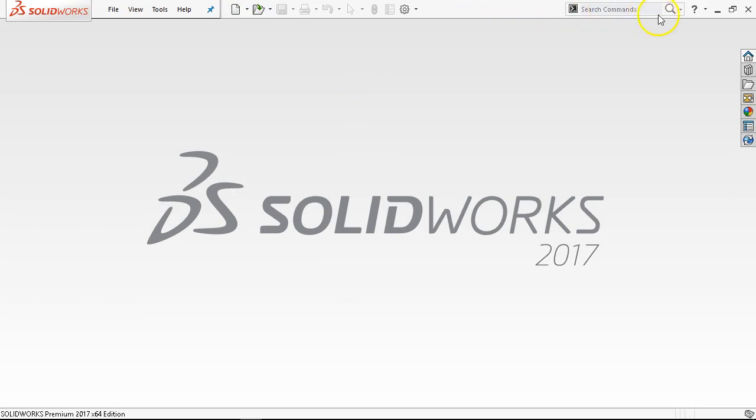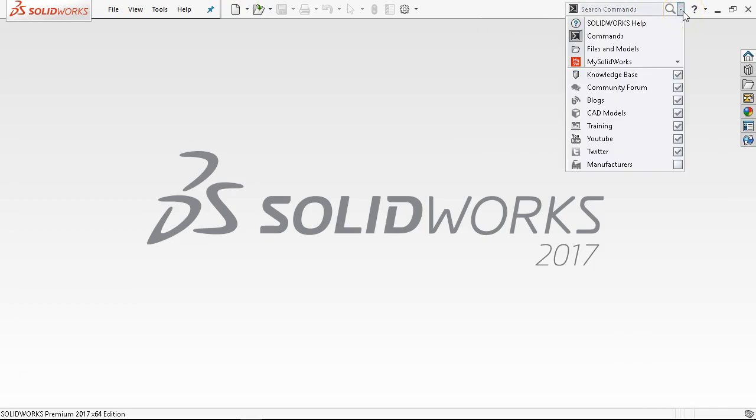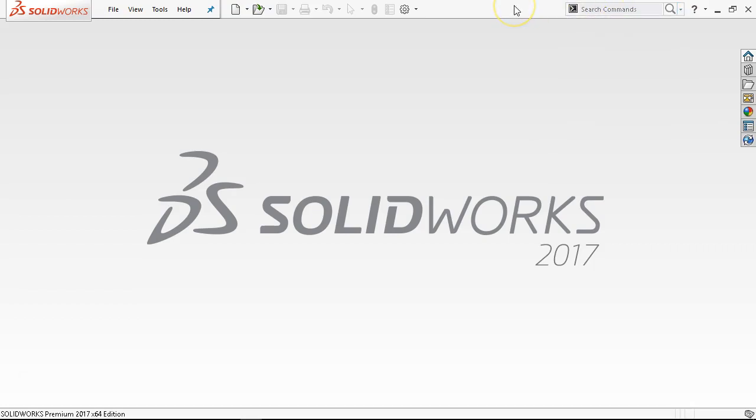On the search commands, if we do a little pull down arrow, showing, I didn't even know it was going down to all of those fun things, but pretty much the search commands I showed you on Tuesday: if I didn't know where to find the line command, I could type in line and it would take me immediately to that command, put it into the property manager, and be ready to go. Usually it's the more obscure commands, where do I want to go to the pull down and then to another fly out to another fly out and try and identify where that location is.